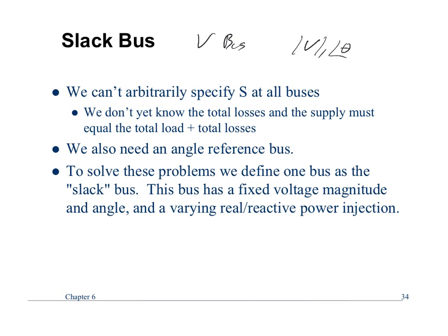You can have multiple references if you want, but you at least have to have one, mainly because of this right here. You'll never know all of the power losses in your system. That won't be fully defined for you. So if you have power lost in a line, how do you schedule all your power at a location? Meaning, if I lose 5 megawatts in a line, based on a certain load flow, I can schedule that power. But then I get stuck, which is, what if it's actually 4 megawatts through there?